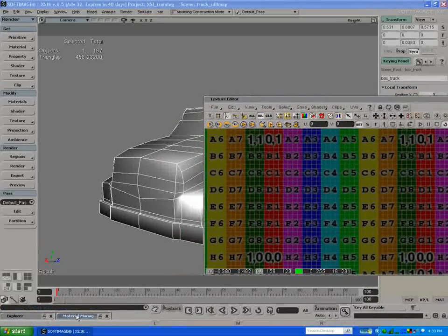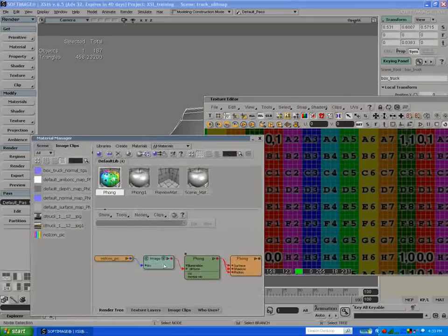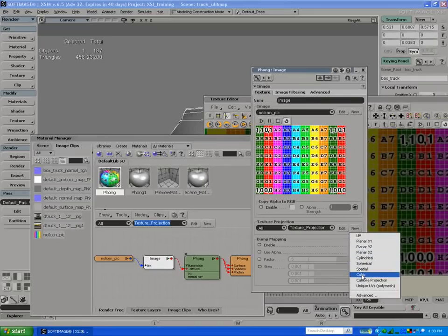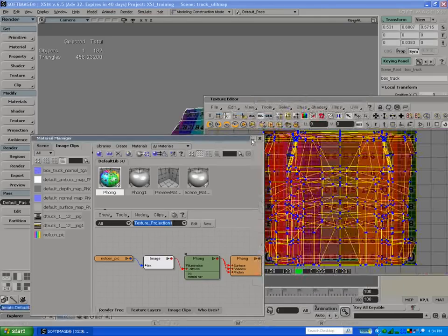And then what we'll do is now go in and create the UVs. We can do this inside the Material Manager, is one option. When we actually pick the objects and look at the image, we can see we can create UVs right here, new, and we could use maybe cubic UVs as a starting point. There's a few other options we'll talk about. So cubic UVs, we'll go in and do a cubic map. You can see here what you got.